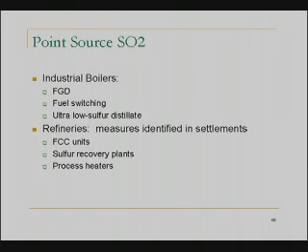For petroleum refineries, control measures have been identified in enforcement settlements. And those enforcement settlements identify sources such as scrubbers for fluid catalytic cracking units, increased recovery of sulfur at sulfur recovery plants, therefore leading to lower SO2 emissions, and ways to lower emissions limits for process heaters.